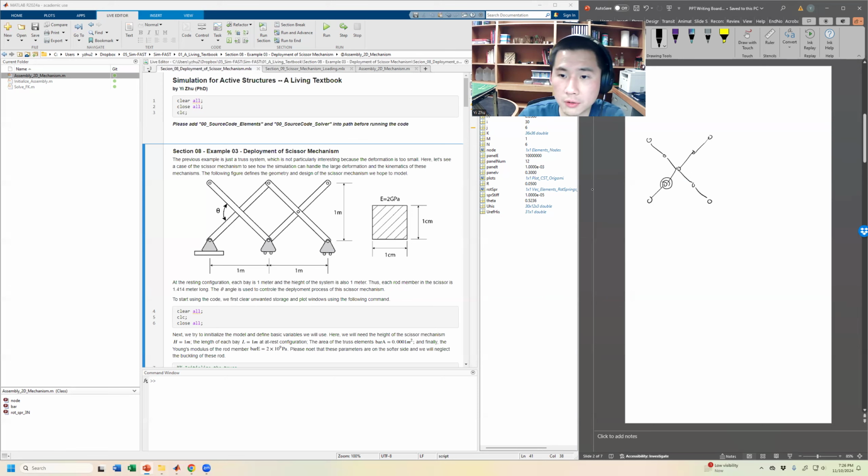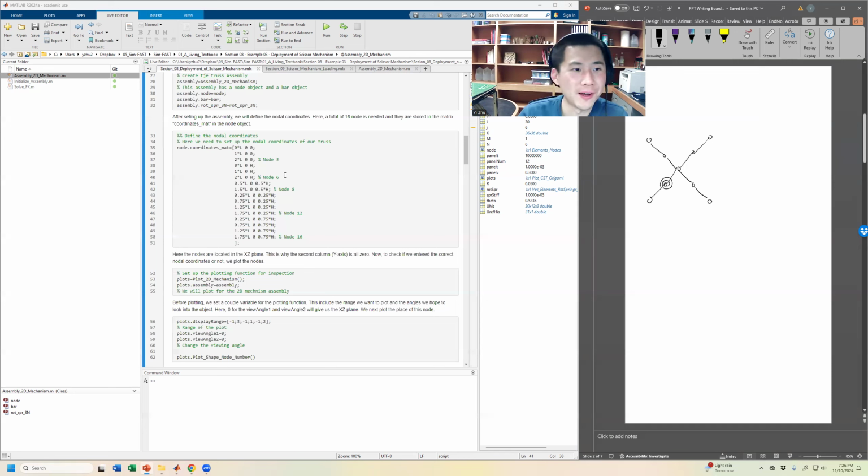So I'm gonna put the rotational spring here. It's gonna give us a way to represent the bending stiffness about these trusses, okay, for these beam elements. And because of that, there are many more nodes compared to what we previously had, but I think this is not too crazy, right?